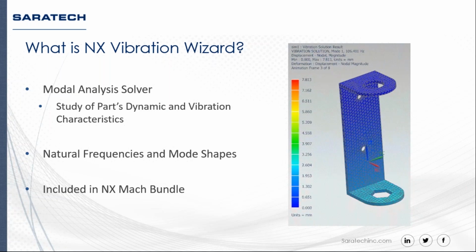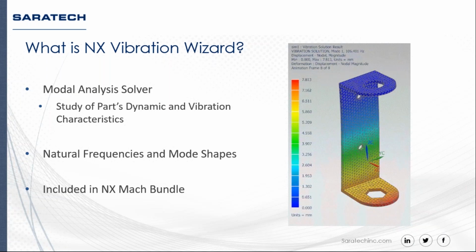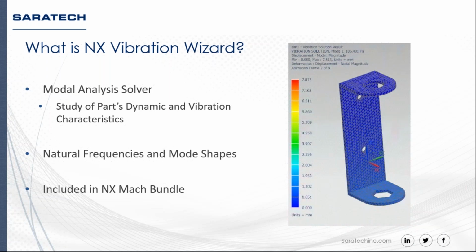If you see the picture on the right, the mode shape is that animation, and then the frequency is the speed of that movement. And this is a little bit more technical, but the reason it could be important is that if you have this part, say the part on the right, attached to, say, a fan that's operating around the same frequency, then